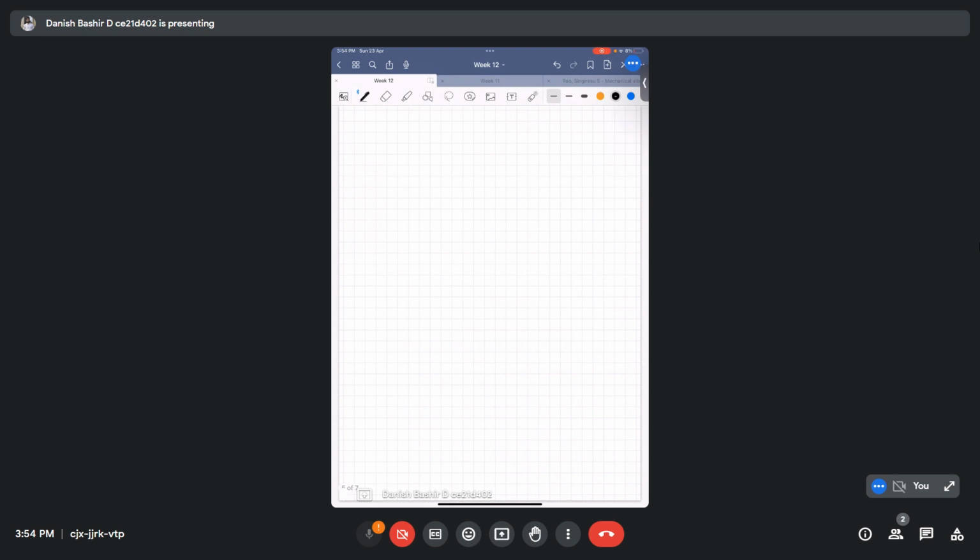We can write sine of theta plus d theta approximately equal to tan of theta plus d theta, which will be equal to dou w by dou x plus dou squared w by dou x squared times dx, not considering the higher order terms.